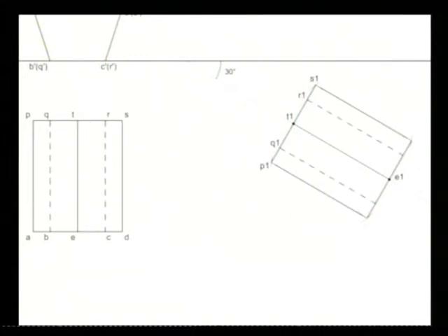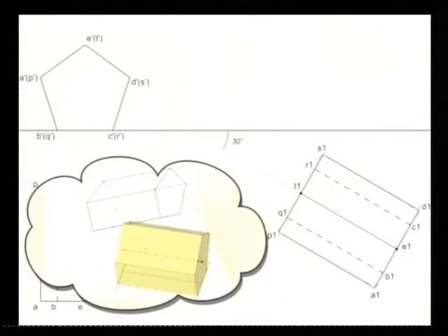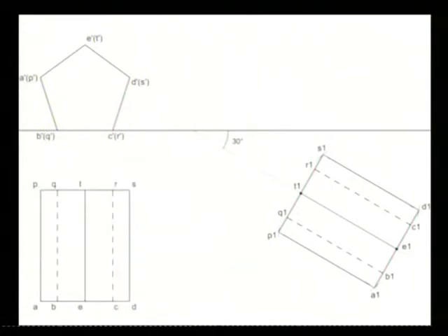What will be the front view in this position? It will be formed by projecting the corner points of the inclined top view vertically above the line XY. Then the horizontal lines are produced from the corner points of the previous front view to intersect the above vertical lines. Joining these points in a proper sequence gives the required front view.